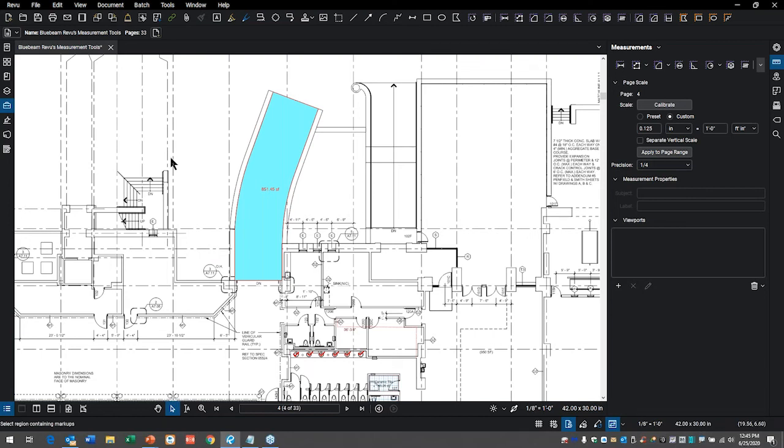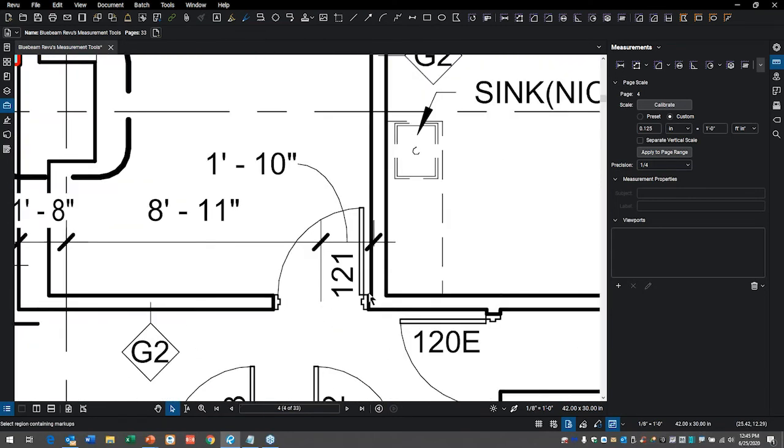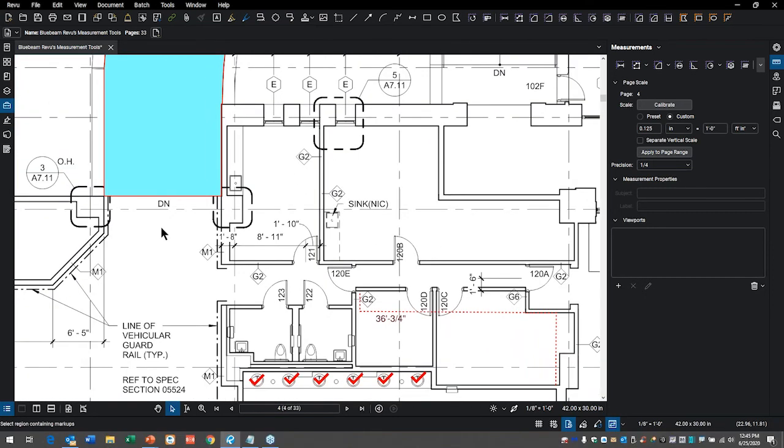There are some issues with line width and things of that sort, especially when you get to door openings, because you're drawing 25%. What actually happens, I'll exaggerate it, is it'll come along, it'll hit that 25%, jump up, jump back down, and come across, right? Because it's reading the thickness of the line. You can come back through and remove those points if you want.